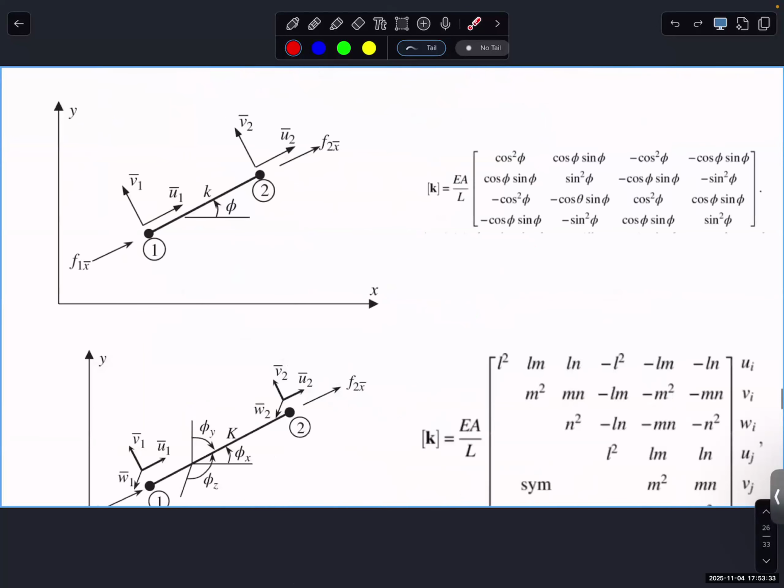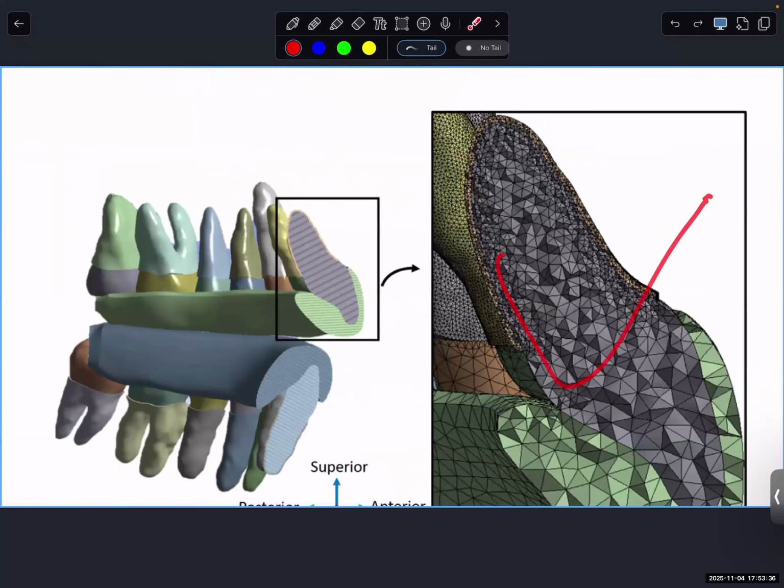So now you can imagine you are doing this, importing this kind of thing in Abaqus. So the key point is that we really need to smooth the structure and make a smaller number of elements. Otherwise, it will not work. Yeah. For context, my model had 1 million triangles. Okay, huge number of elements. That was right. It sends it to the cloud, so no matter what. Like you ain't got a supercomputer.